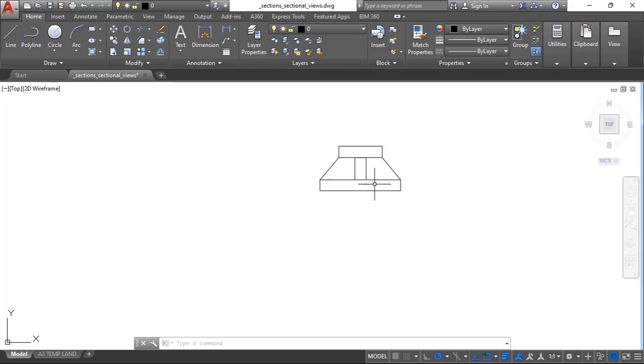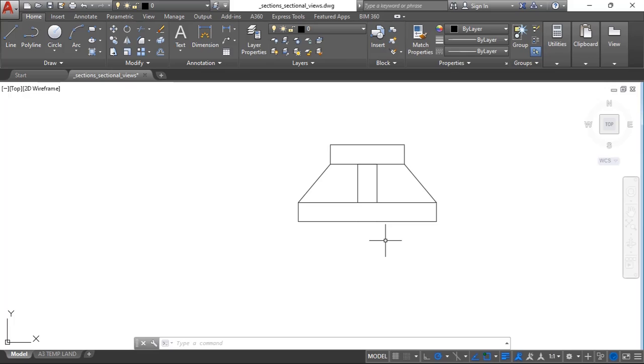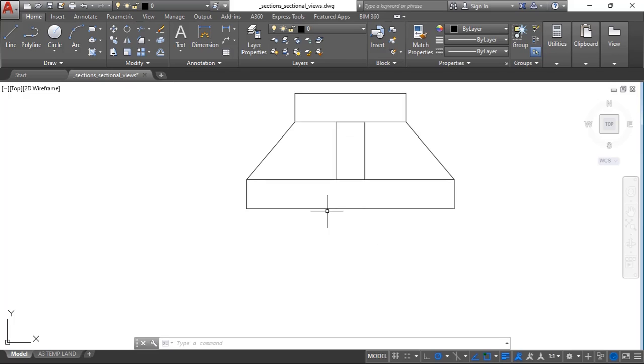So what I'm going to do is to project the lines downwards and produce a plan. Then I'll have to rub off these because they are not required, and this as well. Okay, yeah, ideally you should start with a plan, project the lines upwards, and then produce a sectional front, whichever makes life easier. Okay, but yeah, in the end you end up with the same thing.